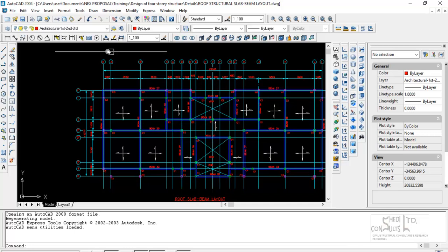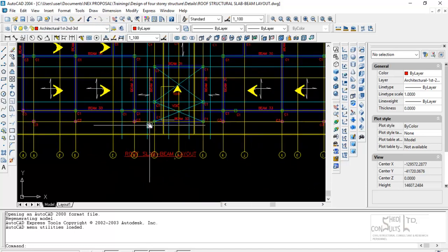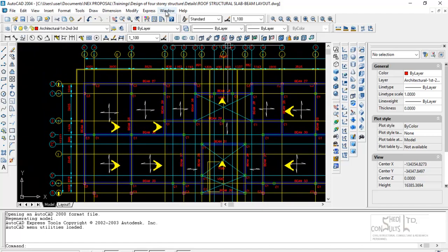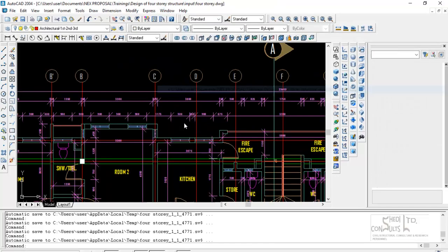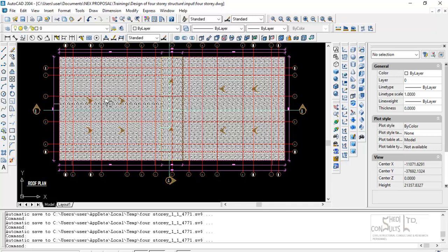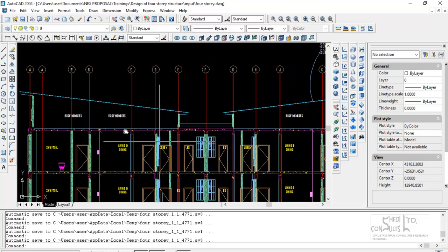What is the guiding principle? The guiding principle for your roof structural layouts is the roof configuration. You need to look at that roof configuration. Let's look at what has been done. The roof structure, based on the architectural design, we looked at it earlier on, but let's look at it in more detail. It slopes downward here, and this slopes in this direction. Let's look at section B. So it says it slopes downwards here, and that slopes in that direction.